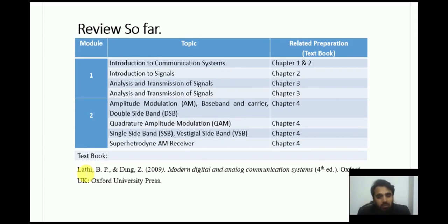Communication systems would not be complete if we don't mention the notion of capacity. There is a definition by Nyquist about capacity for a noiseless channel, and Shannon talks about capacity in the presence of noise. That is, the capacity is equal to the bandwidth times log of 1 plus signal to noise ratio, SNR.